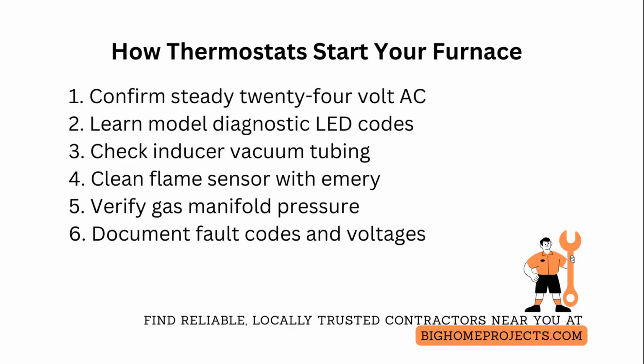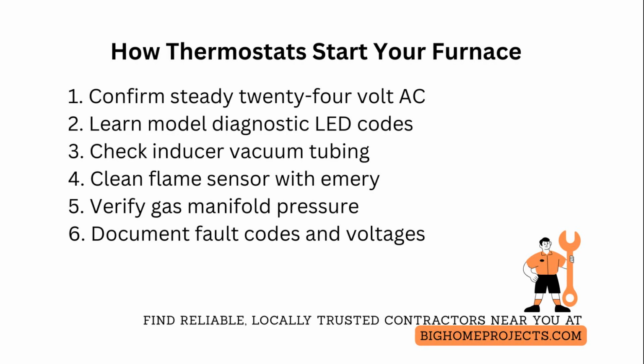For field troubleshooting, always document the exact LED fault code, sequence timing, and measured voltages so you can correlate intermittent faults to wiring or failing components rather than replacing parts blindly.